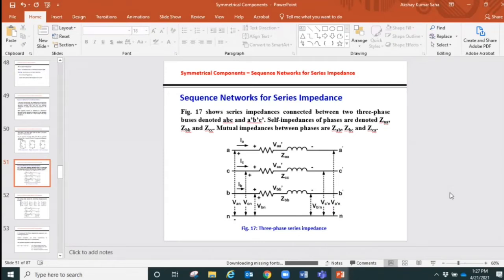It has just resistance and inductance in it for each phase, and then we are connecting the load and the generator via a three-phase line. That line is nothing but representing a series impedance, because each of those will have some resistance in them and some sort of inductance. The inductance might be very, very small. We can neglect it for practical calculation, but it's still there.